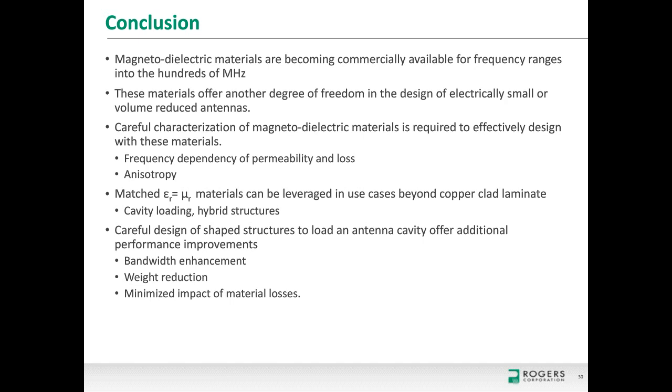Okay, next question. Can you elaborate on the anisotropic nature of the materials? Sure. So what you have is a ferrite platelet that's non-spherical, that's going into a polymer matrix, and it tends to orient as you're going through any sort of process step. So you have a higher permeability in the material in plane.